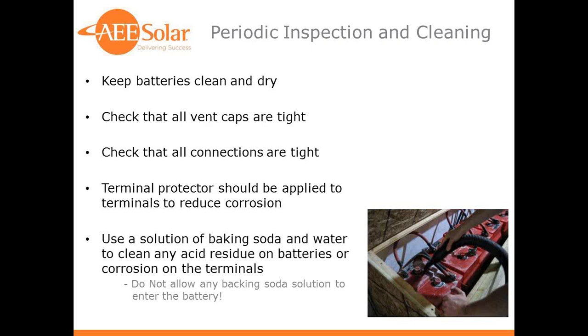Make sure the caps are tight. Make sure all the connections of the cables are tight. Loose connections can overheat and cause meltdown in the connections, so make sure they're good and tight. It's a really good idea to use a terminal protector on the terminals to prevent corrosion. This is particularly with flooded batteries. Petroleum jelly works well, although it's kind of messy.